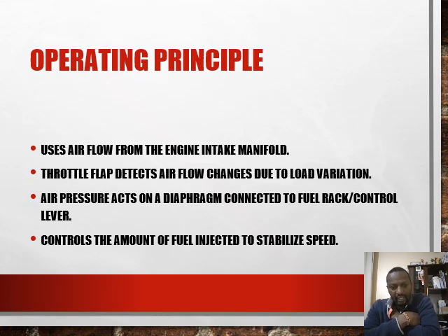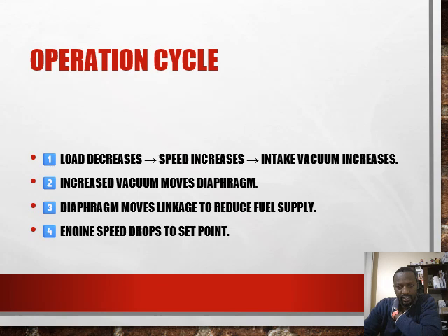So it is this air pressure difference that acts on the diaphragm that is connected to the control rack. And then this one controls the amount of fuel injected to stabilize the speed. So let us look in depth and see how this actually operates.